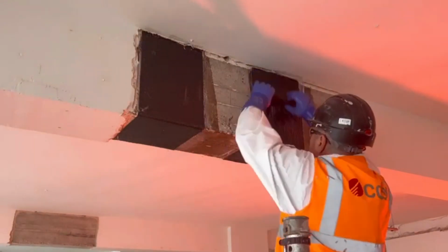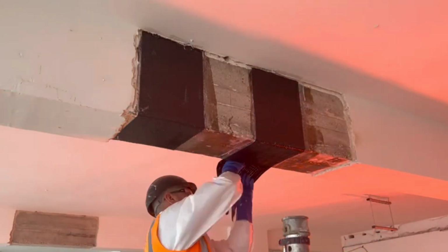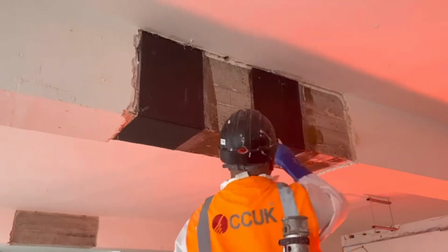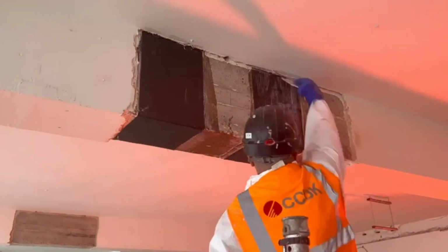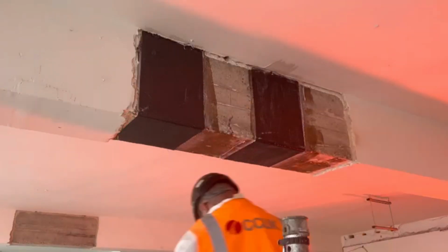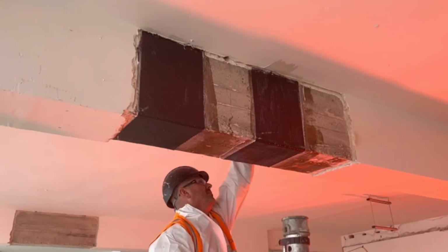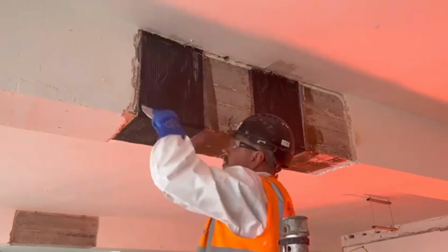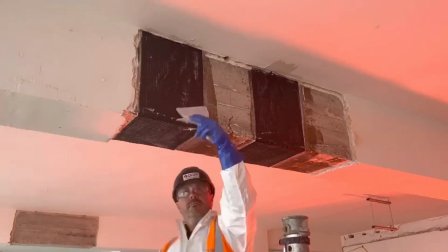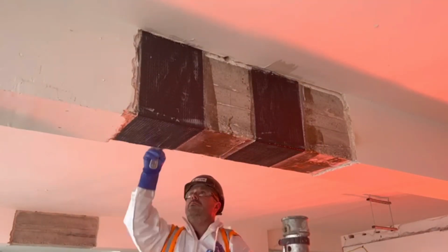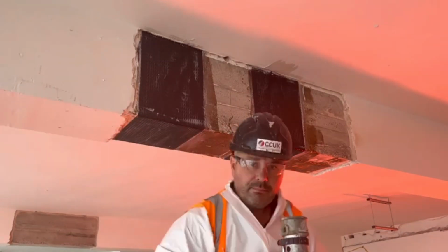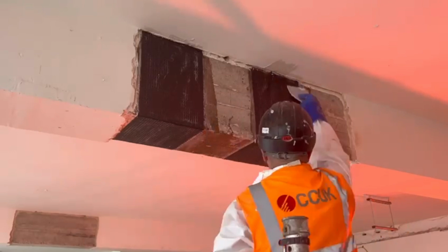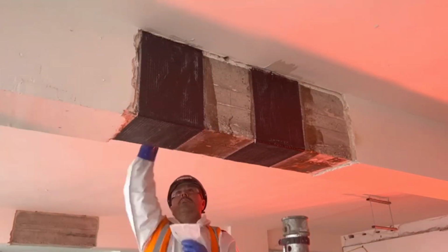And the other important thing to note is that there are limitations on how many layers you can apply in one day or one shift. So if it's a vertical or overhead application, you're limited to apply 3 layers. After that, the saturated weight of fiber could result in debonding before its initial setting. So you leave it to become touch dry. So usually what applicators do, they apply first 3 layers on day 1, then they let it cure, then they come back next day and apply further layers if there are more than 3 layers. But in this application, it was just 2 layers, so everything was done in one go.